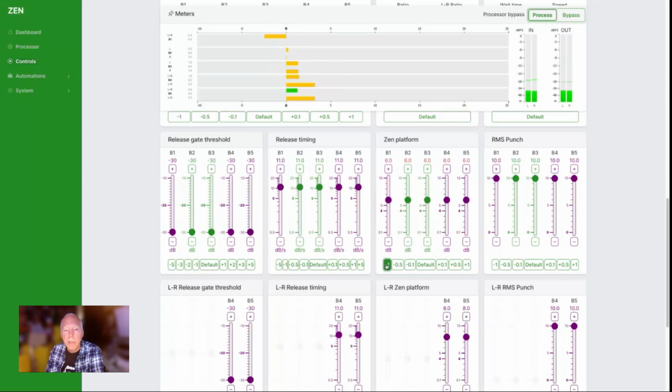And if you go the opposite direction and make it a much smaller window, then you can see there's much more release activity. And it happens to make the gain change a lot more often, which can be a positive or a negative depending on what the programming that you're creating requires. So normally around 5, 4, even 3 is a relatively useful wide range of input level variation allowed. But at the same time, it does control when the audio goes outside of that window, and it will release if it goes below it, and it will attack if it goes above it.